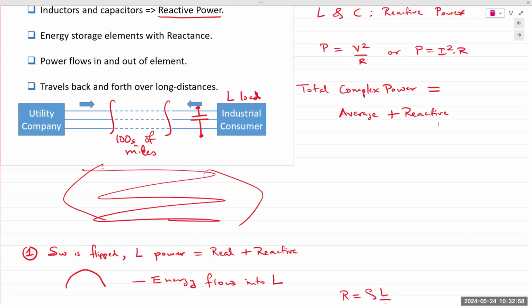Okay, so think back to lab 7, or if you're not taking the lab, think back to chapter 6, resonant circuits. What happens there? At resonance, what we said was the impedance of the capacitor and inductor are exactly the same in magnitude, but opposite in phase, so they cancel each other out. So the output across the resistor goes to maximum. Okay, that's one way of looking at things.